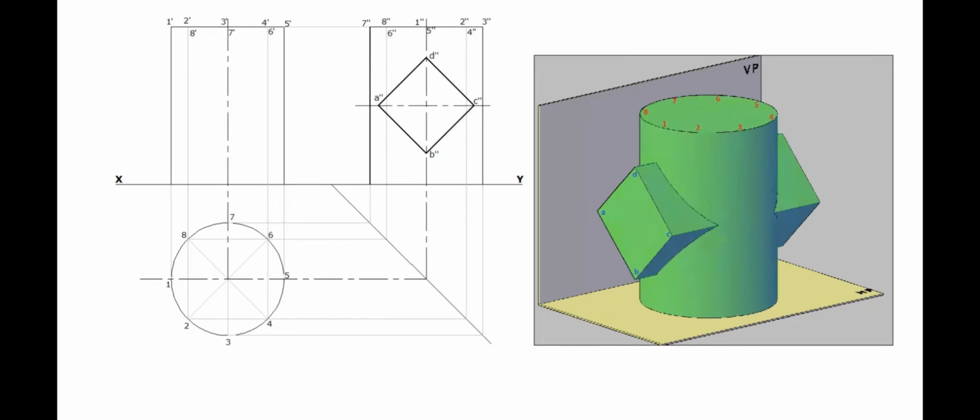In the side view, all lines are visible dark lines. There are no invisible edges. To draw the elevation, the corners of the square can be projected horizontally. Maintain half of the length of the prism, 35 mm, to both the sides of the axis of the vertical cylinder. Name the longer edges as A dash, B dash, C dash, and D dash.